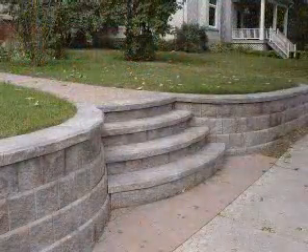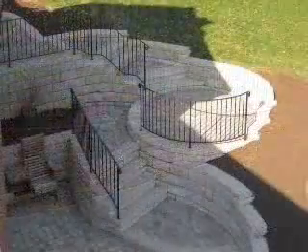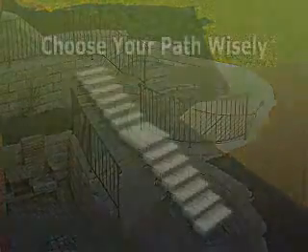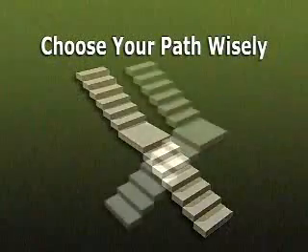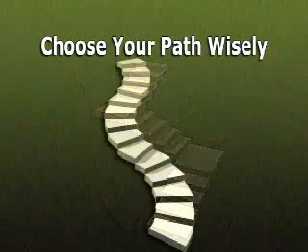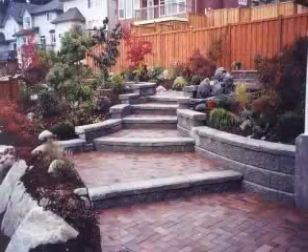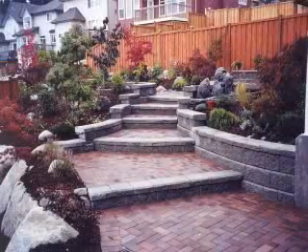When building stairs, choose your path wisely and find the most natural path to maintain a comfortable rhythm to your stairway. You can break up long sets of steps with landings, add a turn-in and a landing, and break up a stair line, or use switchbacks or serpentines to meander up the hill. Tackle your slope by matching your stairway design to the natural grade of your slope.